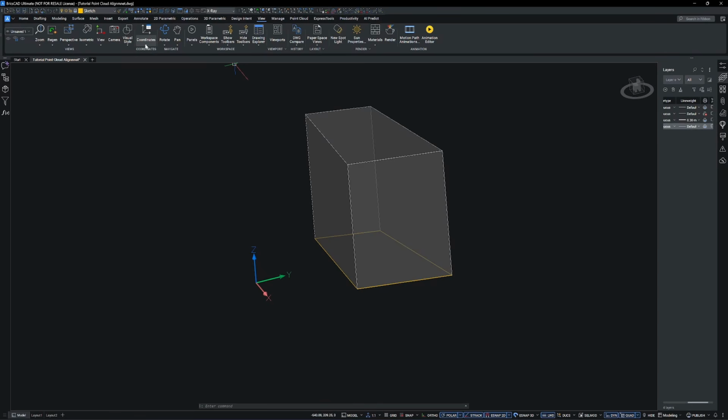The next setup that you have to set is clicking on the view cube here, click on the visual style and scroll down to here. The default setting was set to WCS, which is world coordinates. You need to change it to UCS like I do here. After you have made this change, when you click on the top view from the view cube, the model will turn into the top view using the current UCS as the reference, not the world UCS.